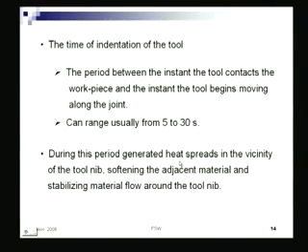During this period, the generated heat spreads in the vicinity of the tool nib, softening the adjacent material and stabilizing material flow around the tool nib, right. That is something equivalent to plate cutting using an oxyacetylene flame.